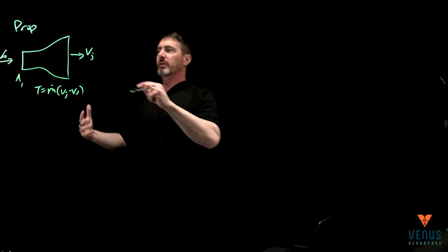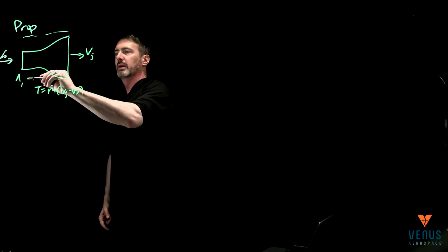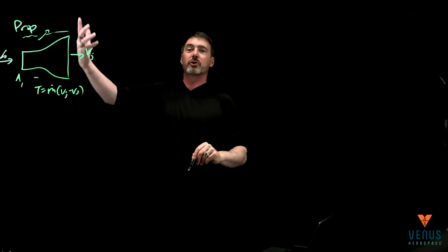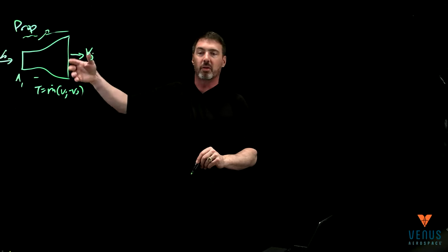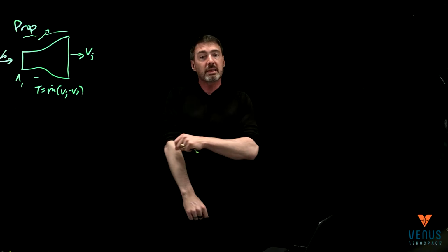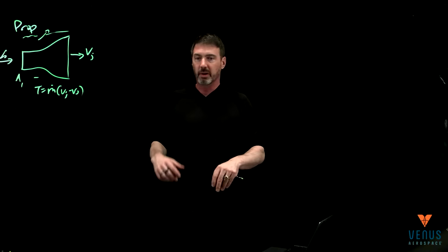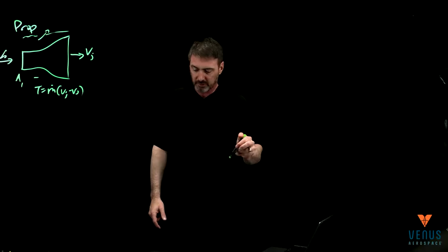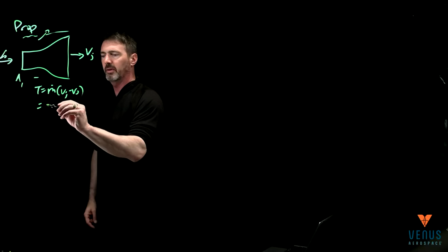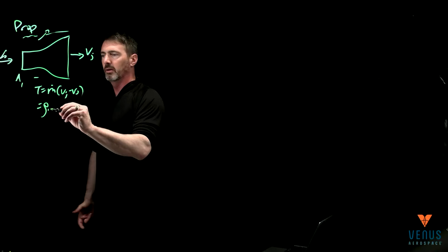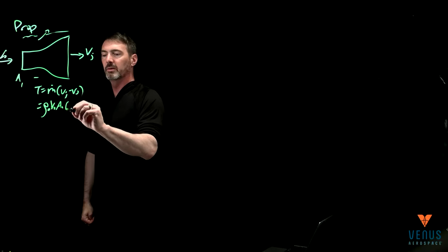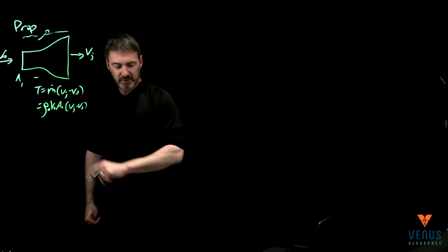From a control volume point of view, that's why I draw this little weird shape. We're going to think about how the air, this would have extra drag because it's shoving the air out and blocking it, and eventually we will track down a lot of these effects. It's pretty interesting to see what you can do with just these high level assumptions. But that's really the main one. If I write this down, that's rho 0, V0, A0, times V jet minus V0.